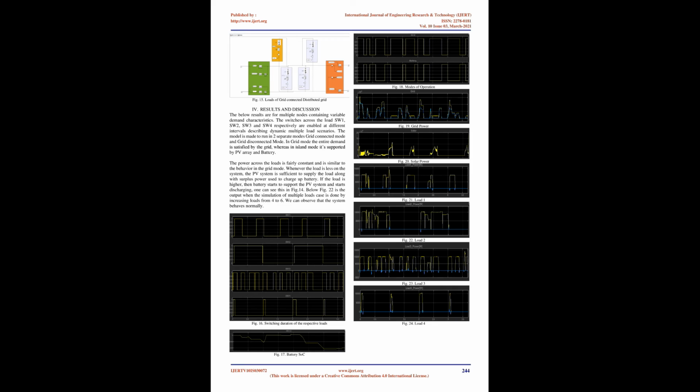8 solar cells are connected in series to form a string, as shown in figure 5.3, wherein all the irradiance inputs are connected to a common port. 4 such strings of solar cells are grouped to make a solar module block. The solar module will have a single irradiance input and 2 voltage polarity outputs.